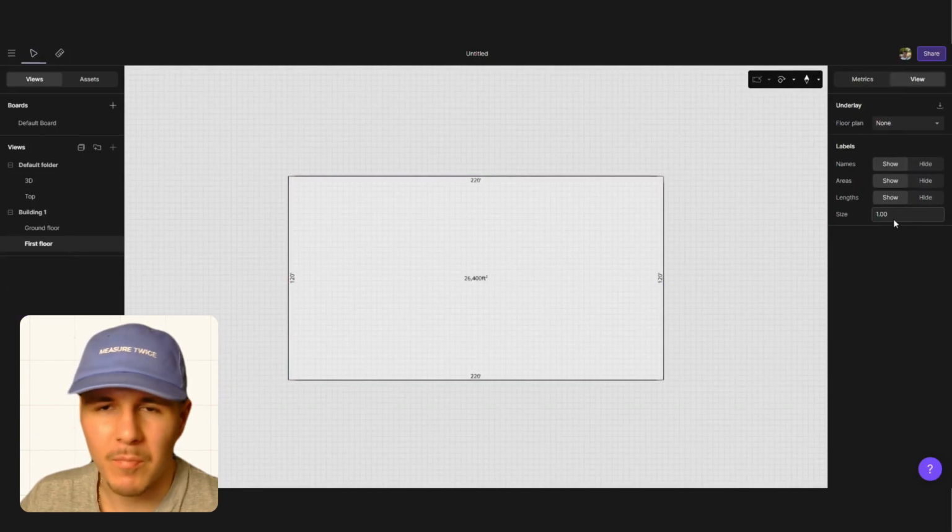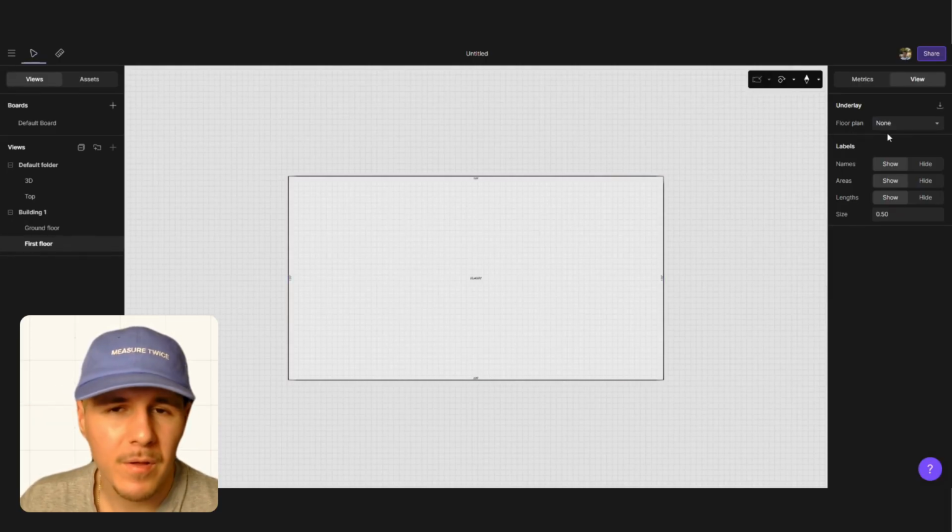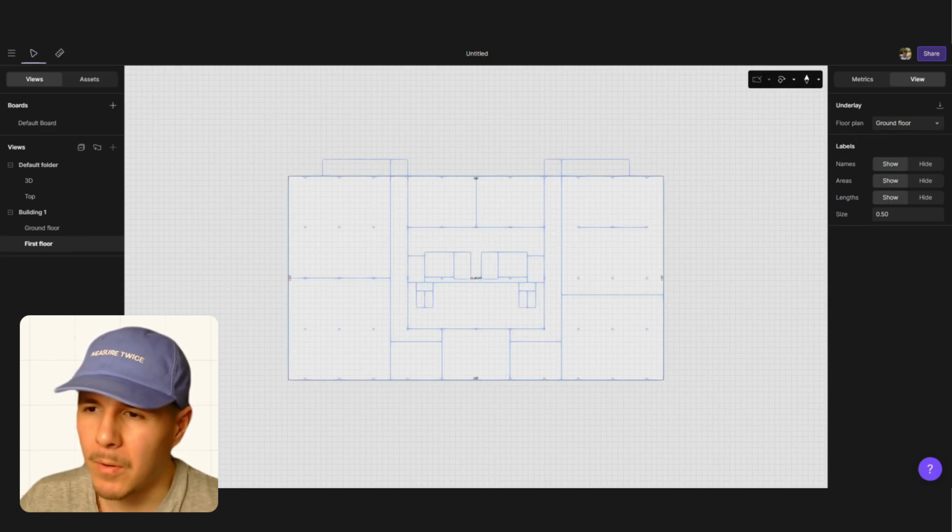Since every floor, even this basement floor, has access to the ground plane, since it has 6 inches of it that are above grade, I think you have an exit at grade at basically any point, which allows you, even though the building is pretty large, to have your egress stairs pretty centrally.